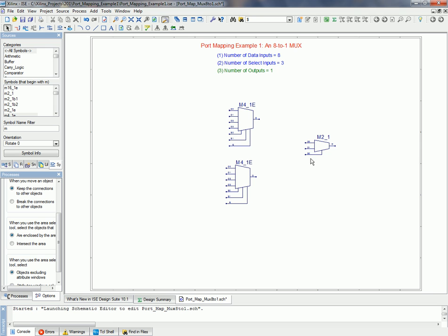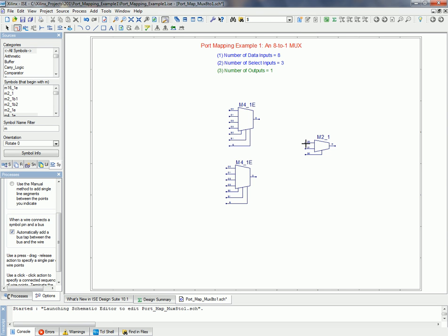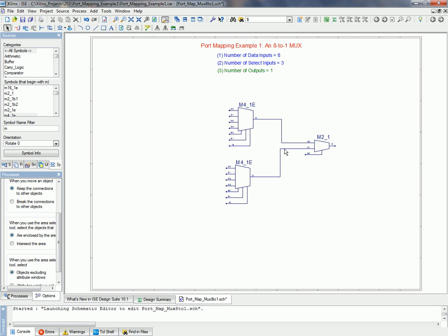So this mux right here, his data input, let's go ahead and put that wire in there, is going to receive one of 4 of the global inputs that will be tied in over there. This is the most significant bit of the mux. That's the D1 input. So when this input gets selected, I will be receiving one of 4 of this mux right here.